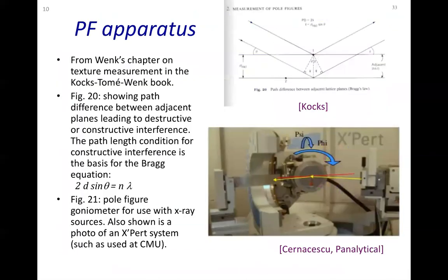All right. The pole figure is classical Bragg's diffraction, but what you do is you rotate your sample in two directions so that you calculate the intensity as a function of this 3D rotation of your sample, and from that you can calculate the pole figures. We don't actually even have the capability at OSU anymore to measure X-ray pole figures. Since the invention of EBSD, it really is a lost art,